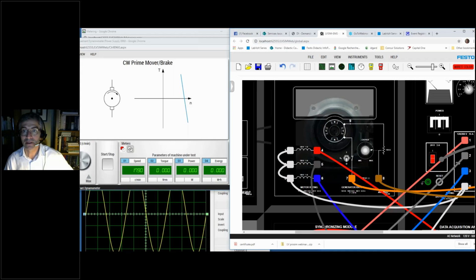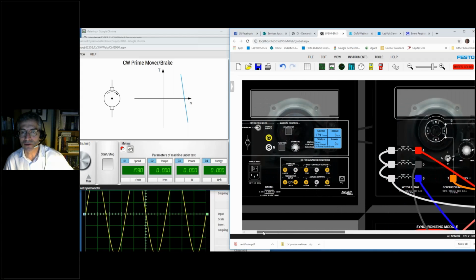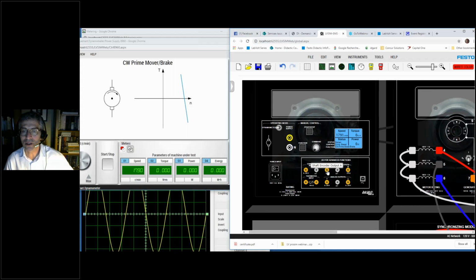You see, typically we should have accelerated here, while in fact, well, it's because of our function here. Yes, that's right. Because of the function I'm using here, if I was using a constant torque function or a constant speed function, I might get an acceleration. But here, since I am setting a specific value with my potentiometer, the dynamometer will simply try to maintain this to the specific voltage that it's using to have the motor spin.